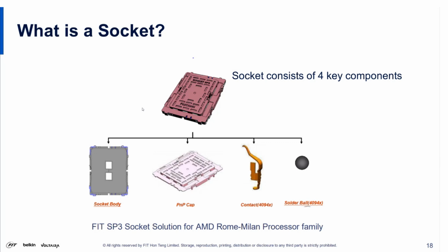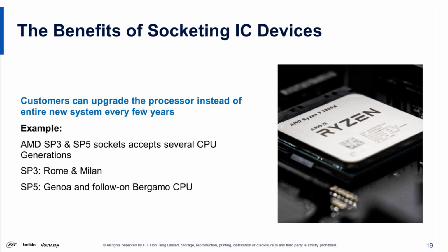processor family. So they have key features which allow us to do stamping and forming, but also insertion into the housing. And then for SMT sockets, you have solder balls, which allow us to reflow the socket and attach it to a PCB.